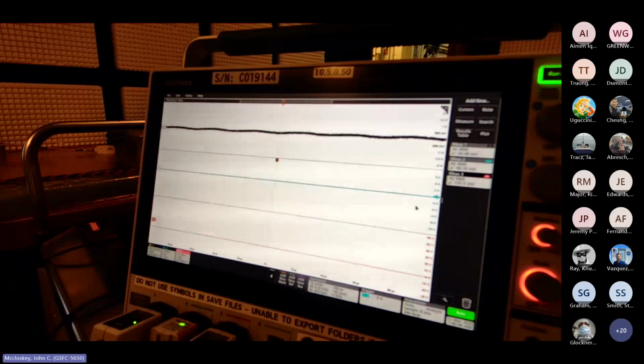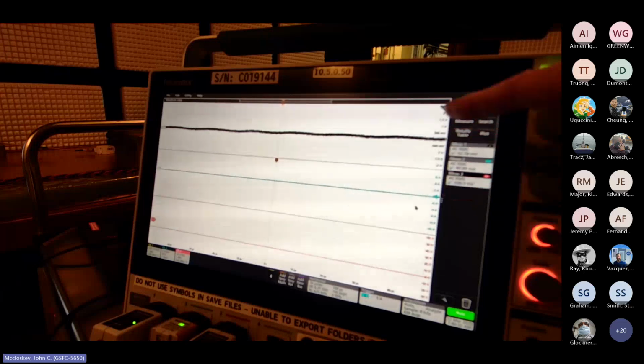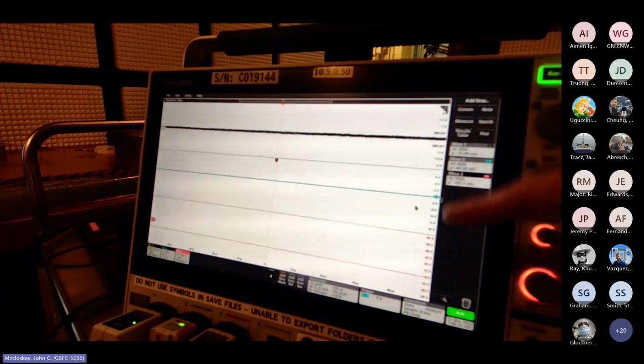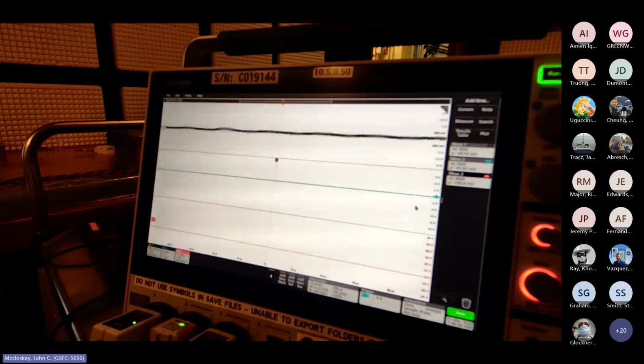But the tendency is to apply AC coupling to a signal like that so that you can expand around the AC component without expanding the DC component as well. And I understand the tendency to do that, but it's not very helpful. So let me turn on the power and then we'll talk about that. So watch all three of these, but in particular the top and the bottom traces when I turn the power on to the EUT.